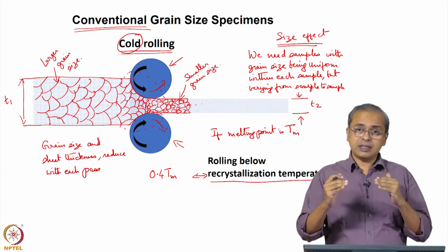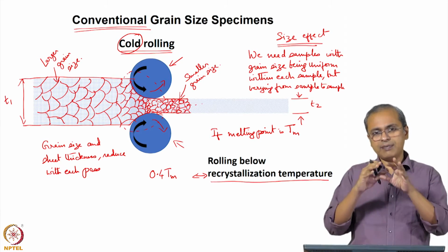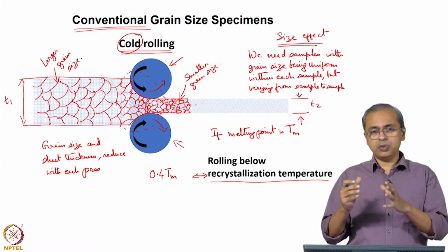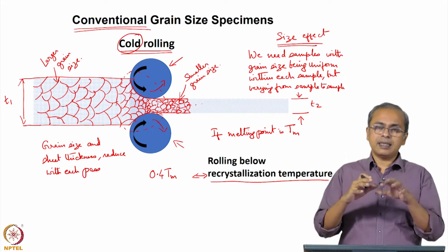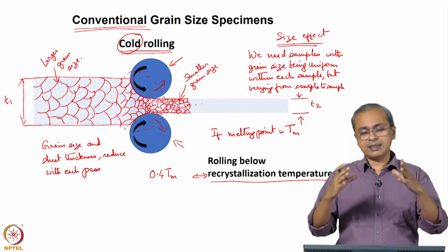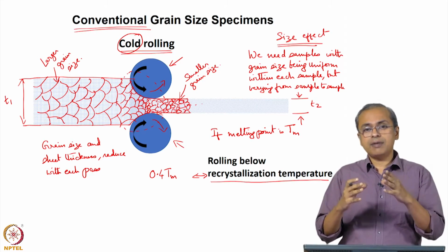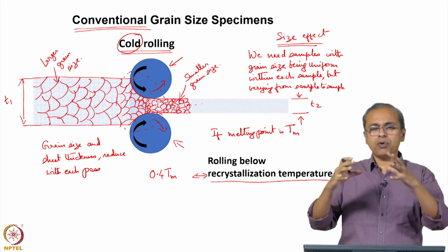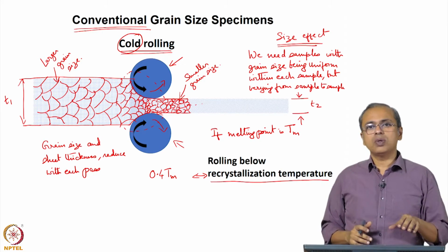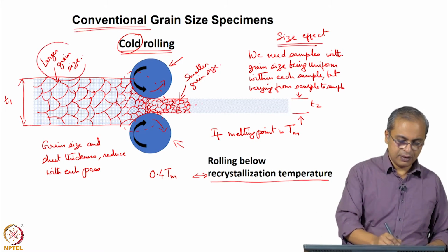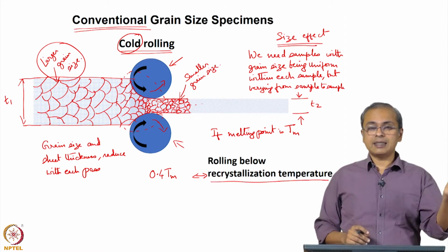What happens is, if you cross this temperature, the small crystals that you have created actually have higher energy because you have created more grain boundaries, and as you know, grain boundaries have bonds that are not satisfied. So, if you have more grain boundaries, that is a higher energy state relative to crystal sizes which are large, which therefore have fewer grain boundaries compared to the volume. If you take it to high enough temperature, 3-4 of the smaller grains will coalesce, come together and form one larger grain. So, you will go back to the kind of grain structure that you have here. If you go to higher and higher temperatures, you will keep getting this grain structure. The sheet may be thin, but the grain structure will be large.